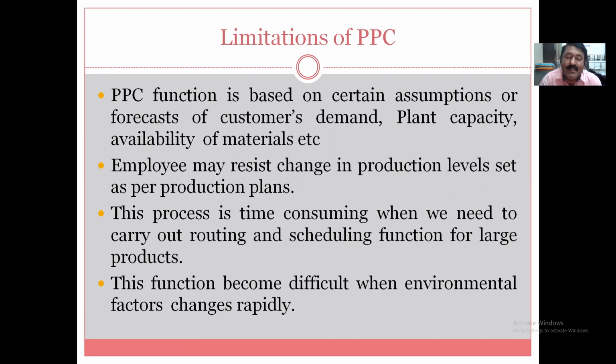He says that 6 minutes are required for each job. Again, if you consider loading and unloading time, then we can produce a maximum of 9 jobs, not even 10. And what is the production plan suggesting? 12 jobs per hour. So this is the variation.